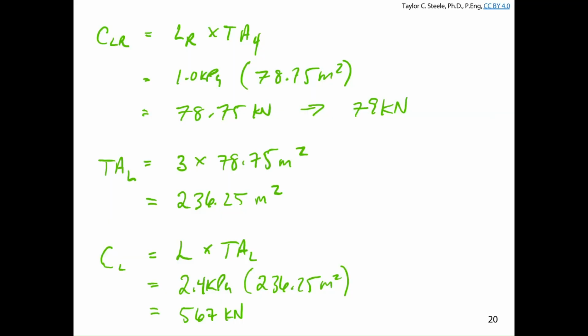So dead loads would imply we're done with the live loads, right? Yes, we do also have to look at live loads, but from a live load perspective, have we considered everything we should be considering with respect to live loads acting on this member? Some shaking heads. What is left for us to consider? Yeah, the potential to have a reduction in this live load.